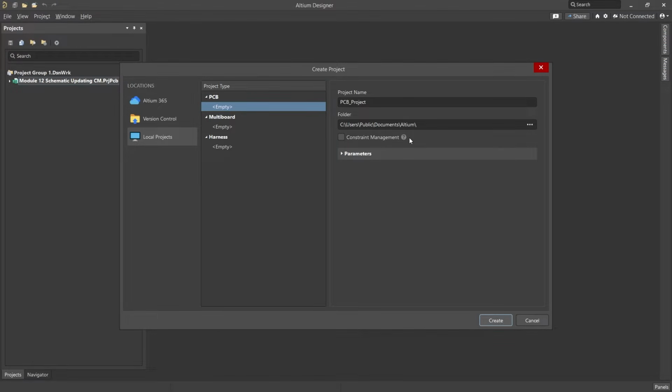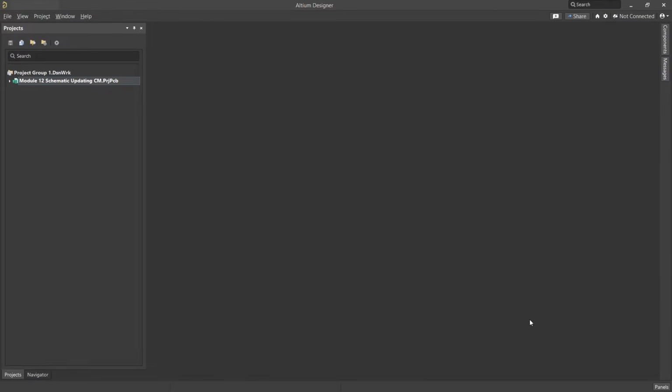Note that if the Constraint Manager was enabled for the PCB project, the PCB Rule and Constraints Editor dialog is not available in the PCB editor. If the Constraints Manager was not enabled for the PCB project, only the previous approaches to define design constraints, use of design directives, and the PCB Rule and Constraints Editor dialog can be used.